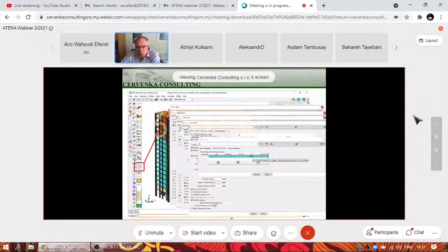This is, of course, possible to do, but sometimes awkward, because if you have a lot of intervals and then you suddenly find out after defining, for instance, 20 intervals that you made a mistake in the supports, it is very tedious to go and make the correction in all intervals. So what is better is to use these additional load cases and reuse the conditions from the first interval.